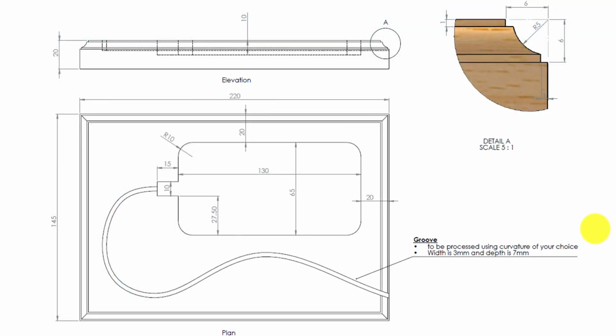Now in some instances, such as the example we were working on previously, you may have to use a tool with a very specific cross-section that is not in the library. If you remember this example from a couple of weeks ago, we did the pocketing exercise, we did the spline, and we sent the 10mm groove, or the flat cutter I should say, along the groove. But we didn't actually have a tool with this profile that you can see in the top right hand corner of the screen to process the edge profile. So we had to create our own profile, and we didn't do that. So let's just have a look at the process involved in creating our own tools.